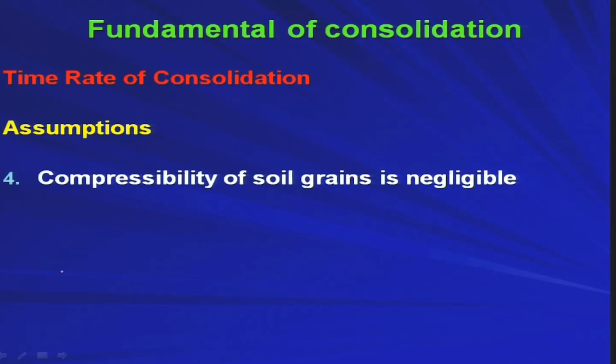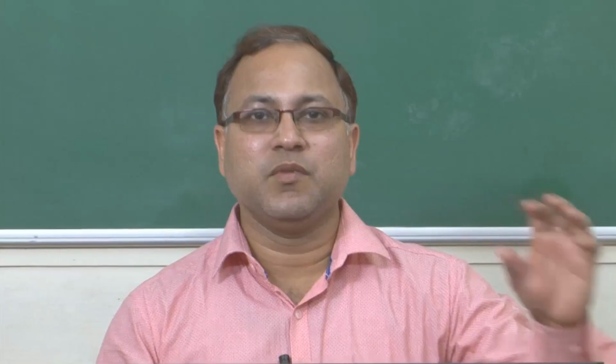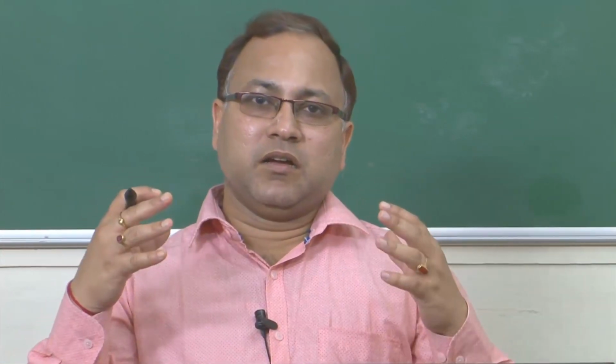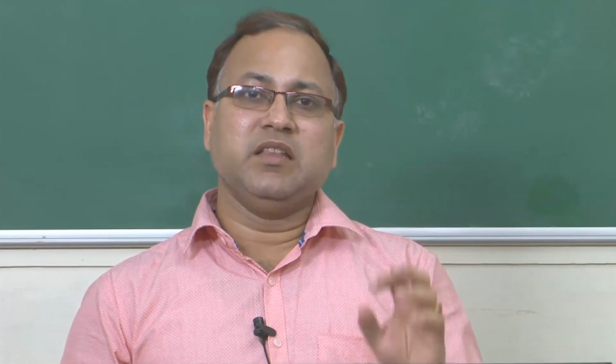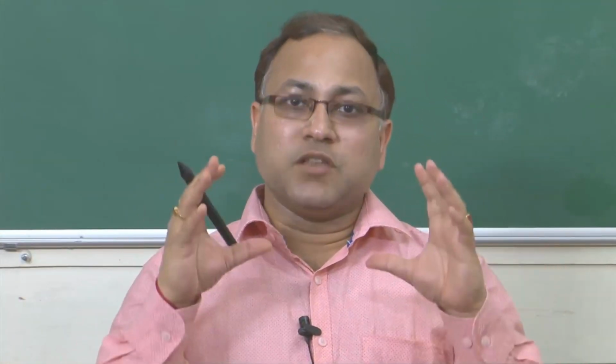Then the fourth one is that compressibility of soil grains is negligible. Frankly speaking, if you go for some higher load application, you will observe some compressibility in the soil particles, but that compressibility is very negligible compared to the compressibility of the soil matrix as a whole. So, the compressibility of each individual soil grain is negligible, and hence we are not considering it in the analysis.